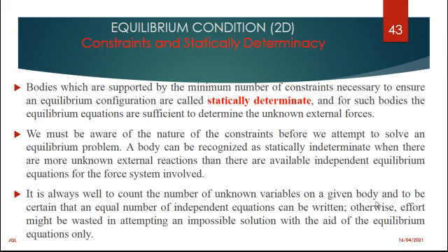It is always well to count the number of unknown variables on a given body and to be certain that an equal number of independent equations can be written. Otherwise, effort might be wasted in attempting an impossible solution with the aid of the equilibrium equations only.